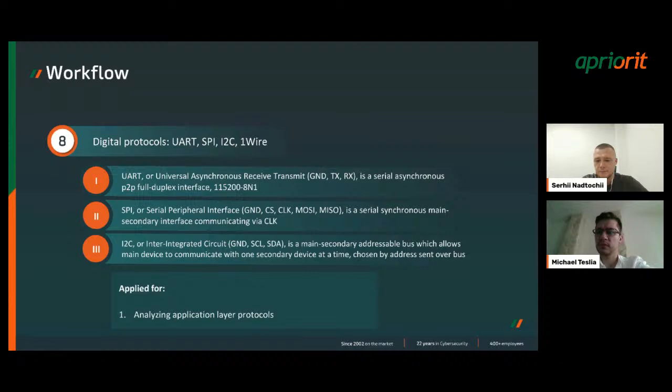So the same thing here: you can use UART, SPI, and I2C as a TCP or UDP packet. But on top of it, while developing your device, you will probably write some application layer protocol. So you will send some streams, some packets, some bytes, and it is your idea how you split and separate them. So yeah, this is good to know about these basics to go on, I would say, to the next step to understand more high-level protocols.